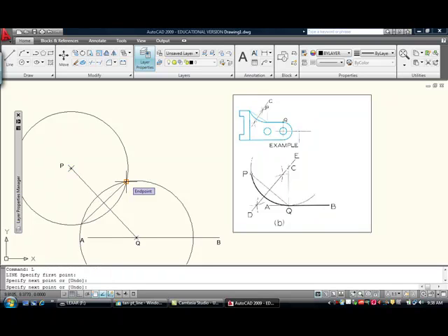Of course, this line is not going to be quite long enough, so I may have to temporarily do something to extend the line. Maybe I'll draw a line over here, and hopefully I can hit it with my extend command. So I go to extend, use that as my boundary, and pick the line to extend. I have to do it in the right sequence, obviously. So now I've got my extended